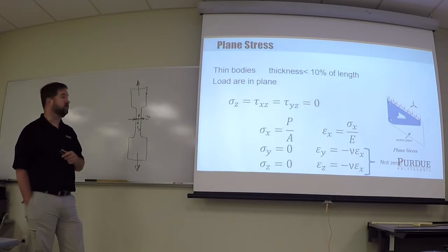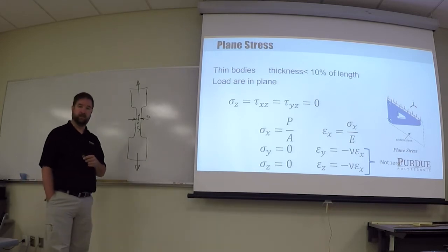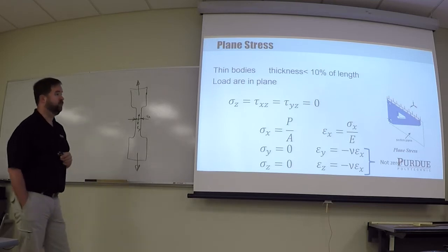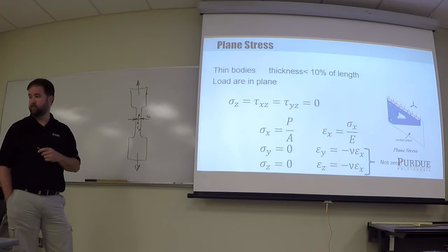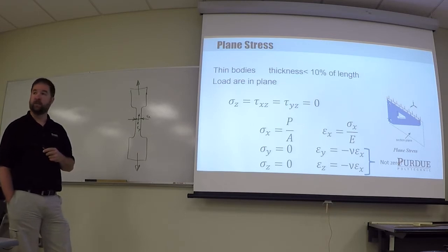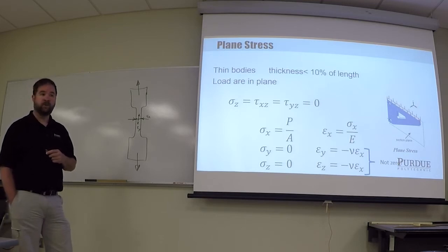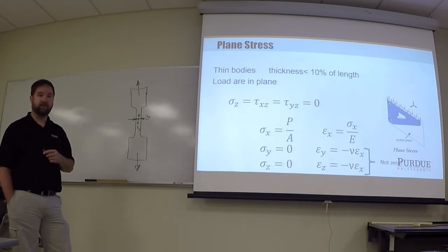For cases where plane stress is applicable, I can use a 2-dimensional element. So, if I have a body where the thickness of the structure is small, I can assume that it is subject to plane stress, and I can simplify my equations. It makes my analysis a lot easier.